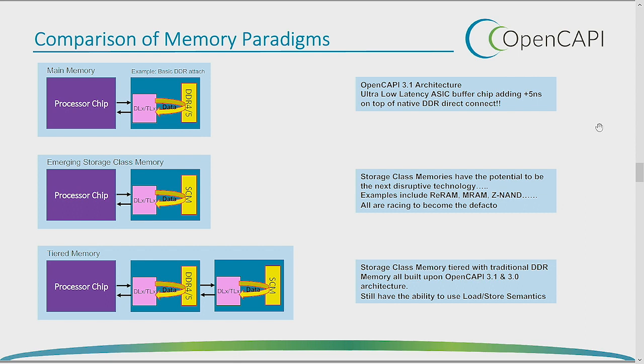But with traditional DDR interfaces, especially in some of these flash-backed devices, you do a write to DDR and there's no acknowledge. There's nothing in the DDR protocol that enables you to say, this is when my write's secure. You just send the data, and if there wasn't an error, life is good. The problem is, you don't know if it really got there or not. Since we have an explicit write acknowledge, that enables much more sophisticated persistence mechanisms in the memory.